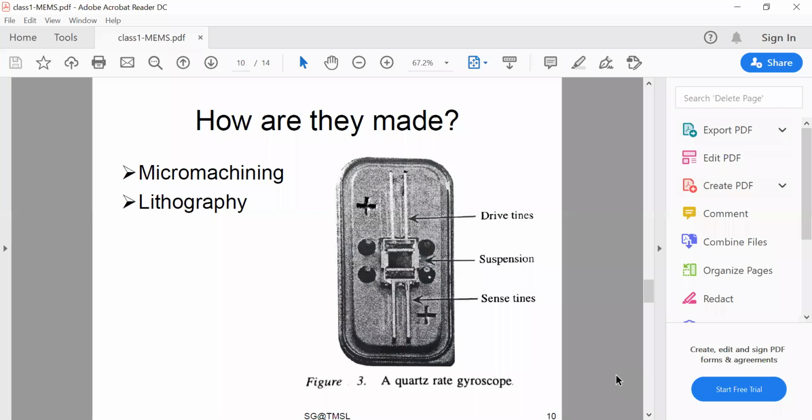They accepted this technique. However, an alternative strategy is to partition the microsystem into subsystems that are fabricated separately, then assembled into a compact system during the packaging operation. In this way they can make, so here it's a gyroscope, very small, where the suspension area is there, a tiny section which can be sensed by the sensor. So it's a MEMS device, a gyroscope.